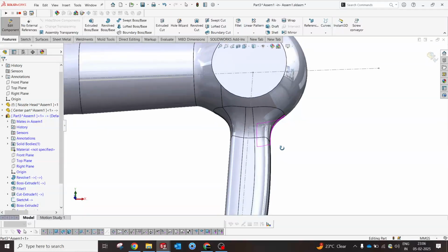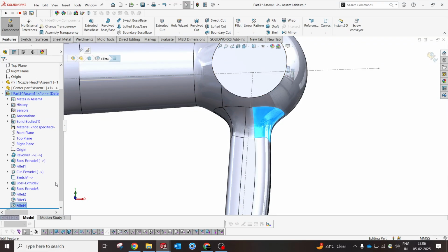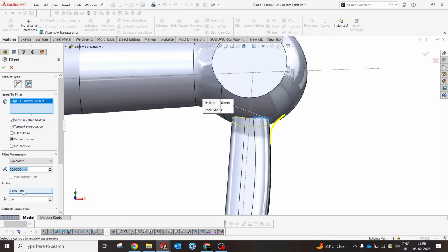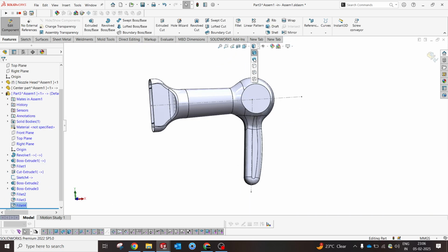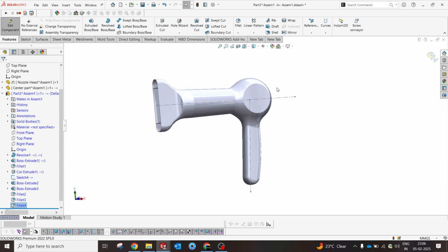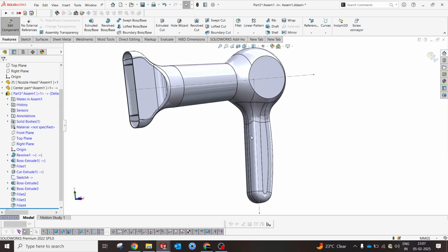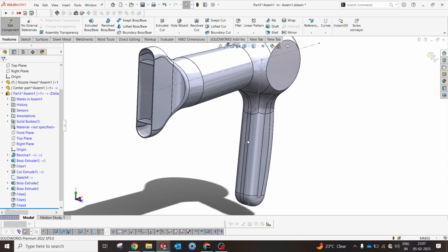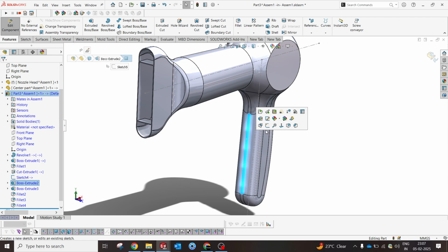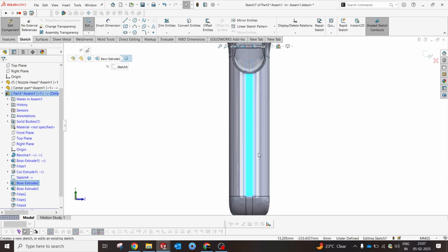So even you can increase the fillets how you want to play with that. Yes, how smooth you can also see, this will show you the realistic product rather than having an edge. You can always select the shaded option to see. Okay, good. Now the handle is ready, so we'll make sure with this by selecting again a sketch.